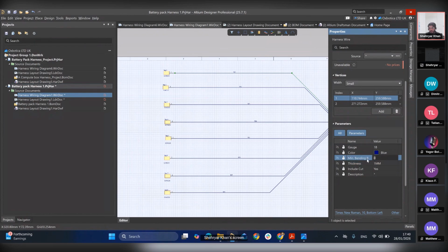Bending radius, minimum bending radius can be calculated by your bundle diameter and all these things, and also the cable diameter. It's something which needs a bit of calculation, and then you can also input that value here, and then you can describe the name of your wire or cable. So it depends again what is the name of your wire. I will choose the name of the wire of the manufacturer. It's a Belden. Let's take Belden. It's one of the famous companies for manufacturing cables and wires.